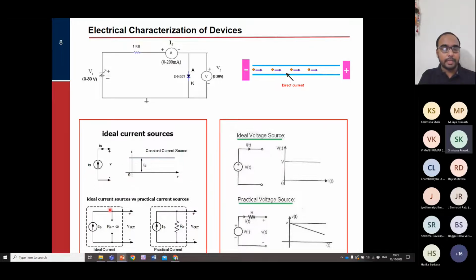So it means that the output resistance has to be infinite, or basically there is no short circuit as such. However, in reality that does not happen. So there is some kind of resistor which you can think of staying in parallel. So the current which it delivers will, let's say, if the load increases, decay down slightly.